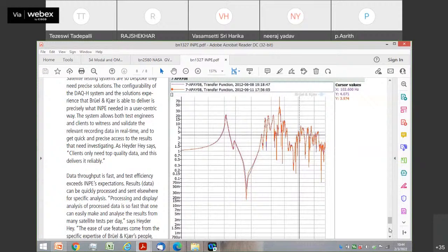Okay, everything else being identical, the cable is okay, maybe the sensor is a problem, maybe the DAS is a problem. Look at the time data of 2 or 3 sensors mounted closely and then start investigating whether under identical conditions and identical sensors there are any issues.